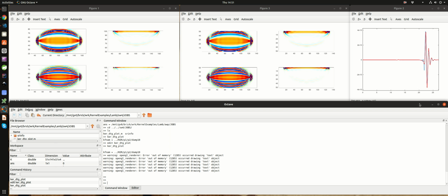So it looks like the Rayleigh wave computed by AWP is slightly more accurate if I am using the same grid spacing, right? So for SW4 it's 50 meter, and for AWP it's also 50 meters. The grid spacing is 50 meter for both cases. But the synthetic seismogram seems to be slightly more accurate for AWP. Right, the red curve is slightly more accurate at the beginning of the Rayleigh wave pulse.